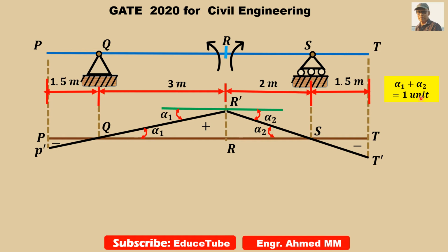Because this total angle, I mean 1 unit, is split between the two triangles. As we can see, it is split in inverse proportion to the base length of the triangles. Very important point to understand. So once we understand this, we can find this R prime, these ordinates.